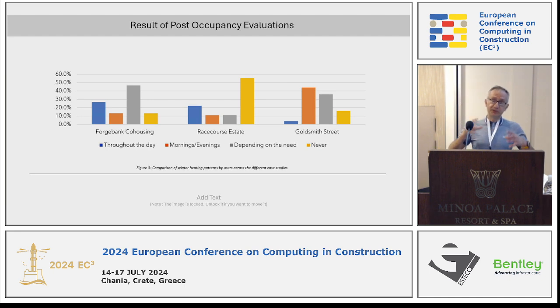So even within this passive house standard, depending on the housing type and the housing design and the orientation of the windows, there's still a variation in thermal comfort. And normally when these houses are designed, they're just handed over, and with a mechanical ventilation heat recovery system, yes, there is a limit to openable windows, but you can't fully open the windows because then you'll increase the heat loss. So it is almost like a very rigid system. It's a very controlled system.